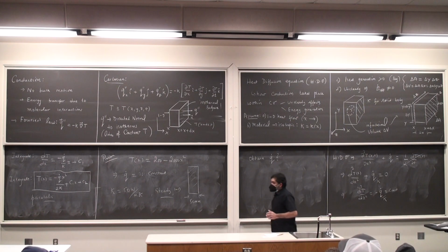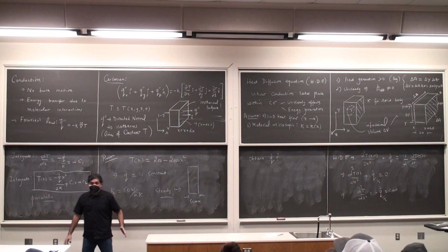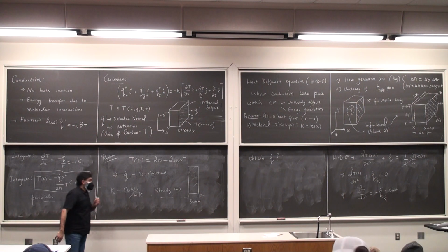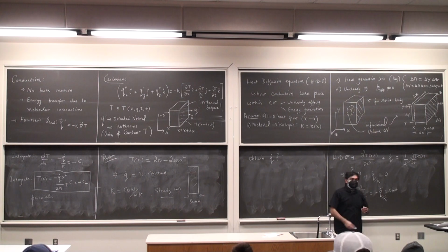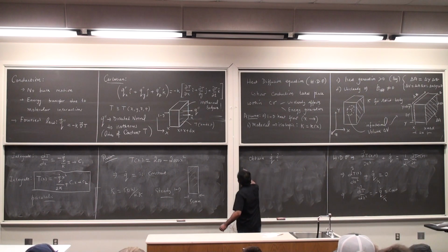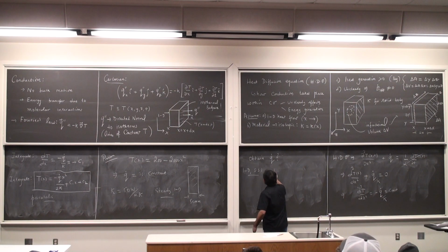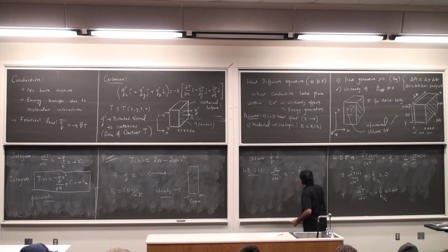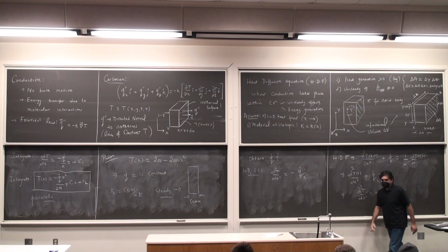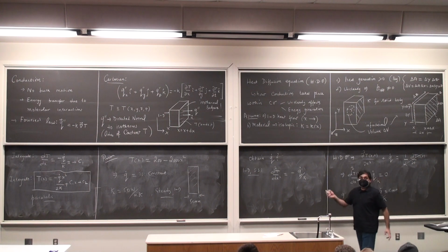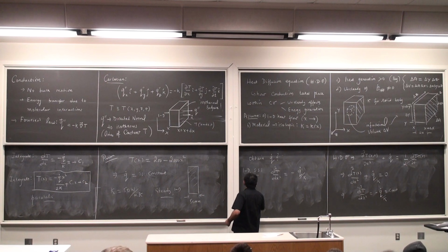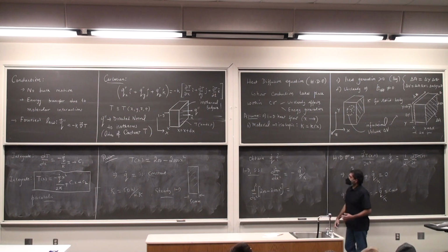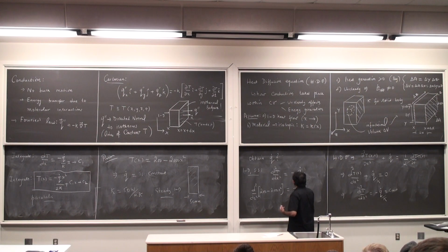And what we will be doing from now on is, without using a computer, without using a calculator, just by looking at the temperature equation profile, we need to know how to sketch the temperature profile. Okay? Q dot, it's fairly trivial because I already have this equation. So from what we did, 1D steady state, minus Q dot by K is d square T by dx square. T is known as a function of x, so this is d square by dx square of 200 minus 2000 x square is minus Q dot, which I don't know, divided by